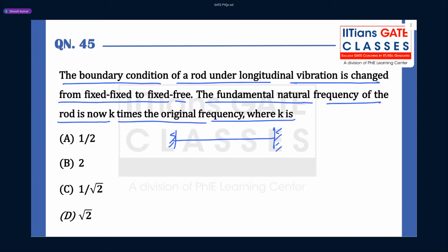So in the last class, we have seen vibration of shaft where both ends were fixed, right? So I told already, when both the ends are fixed, what is your boundary condition? At x equal to 0, what will be u? Anybody? What will be u? At x equal to 0, u will be 0. Same at x equal to L also, u will be 0. So these are my boundary conditions.